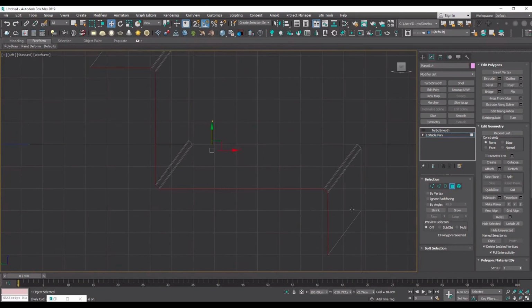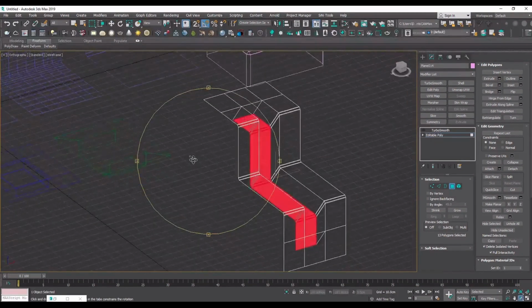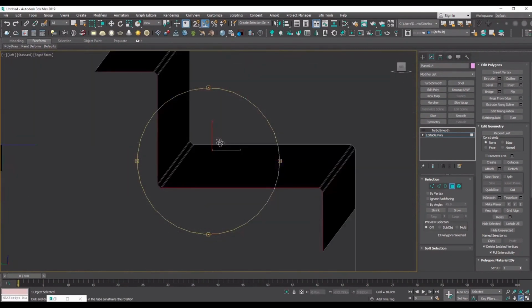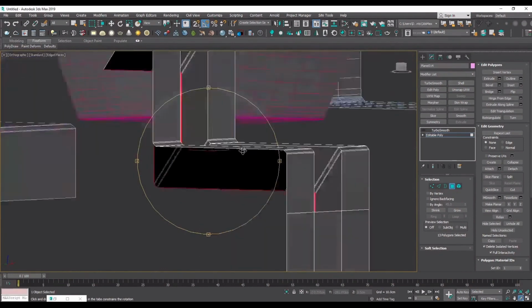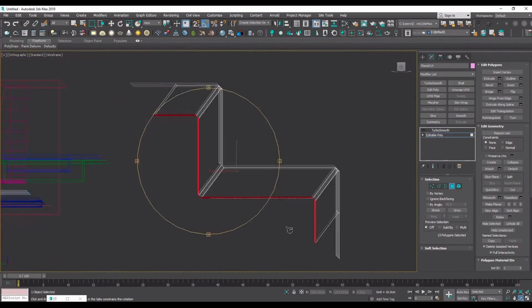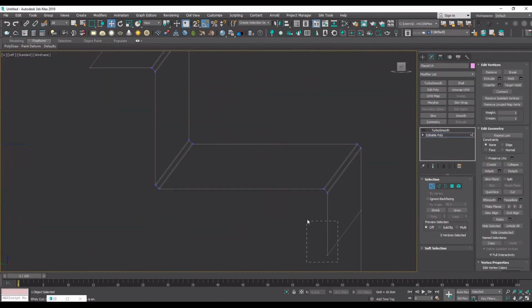If you take a look, you see that the extrusion itself has worked fine, yes, but because of the angle that we're on, all of our edges, even the last ones on the top and the ones on the bottom, are being diagonal too. They have the angle to them. So the thing is, we have to manually put them in the place we want.